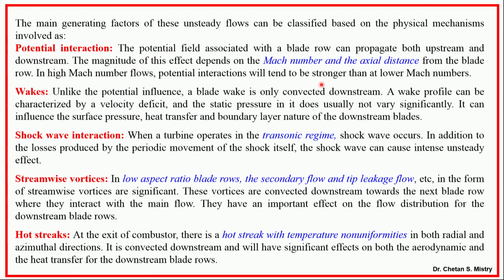So, now if we consider this, we need to understand the physical mechanism for the unsteadiness. That is because of potential interaction. Now, what is that potential interaction? We have the gap between your stator and rotor. That particular region is what has been defined as the potential flow field. My Mach number and the axial gap between the rotor and stator will decide my potential interaction.